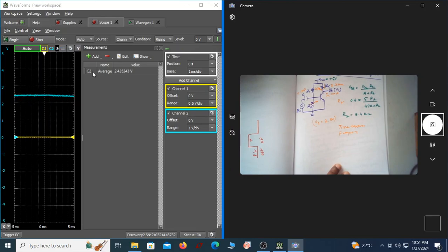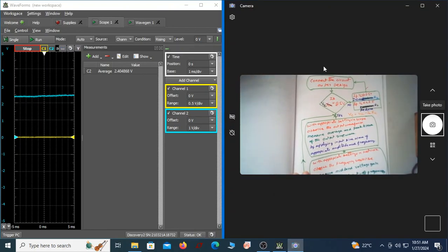Okay, now this is fine. It's almost 7K. So I'll make this 100 ohm 0 and make it 7K. Now you can see you're almost there. So it is 7K, and it is around 2.4 volt, meaning I was able to achieve this. I have connected it, and now VC is close to 2.5. Let me see what happens if the value of VC is too much.